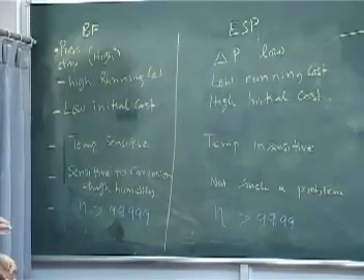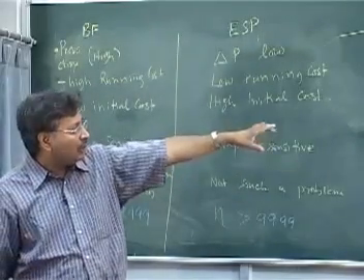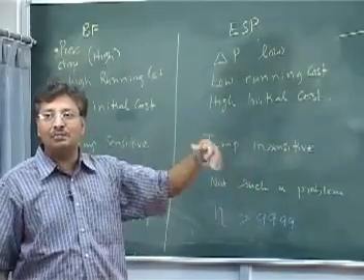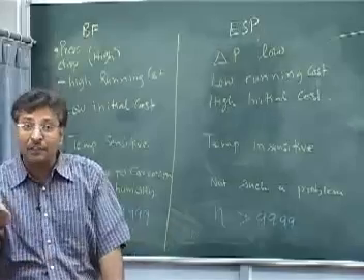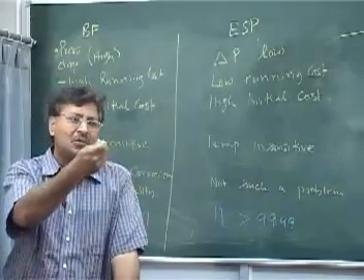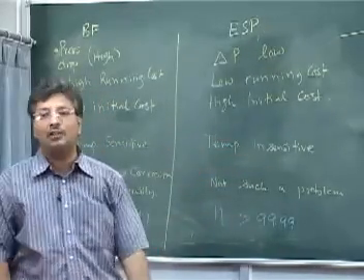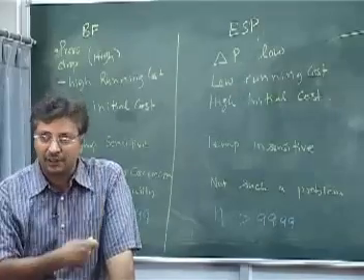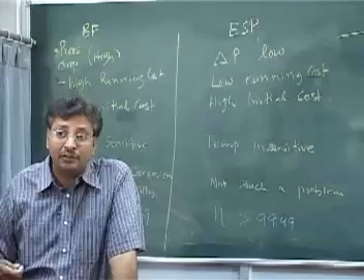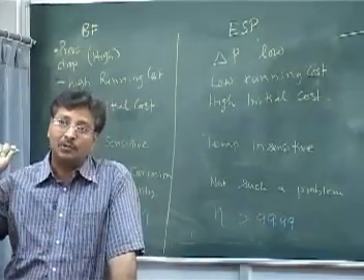But ESP is still considered to be more robust, because with bag filters you have to do operation and maintenance constantly: bag tearing, the life of the bag, the running cost. Bags have a limited life, whereas once you install an ESP, you forget about it for 10-15 years. The fabric filter will have a life of 1, 2 or 3 years, and you always have to maintain inventory so you can quickly replace the bag, whereas with the ESP, you make it and forget about it.